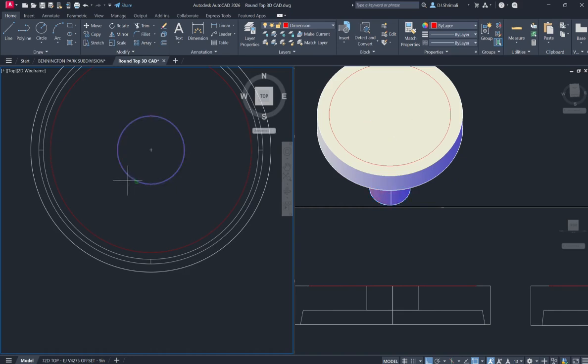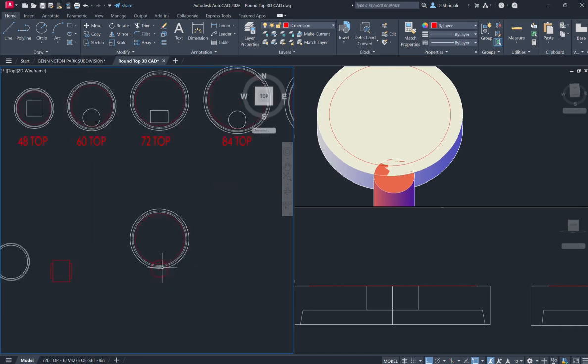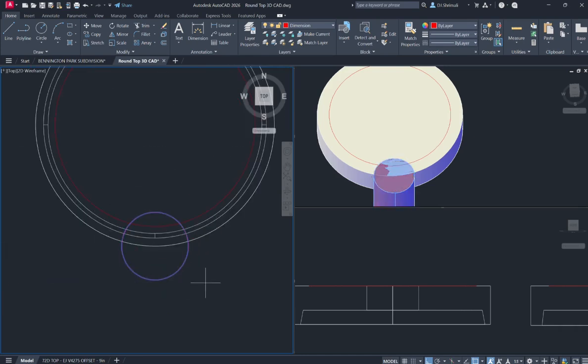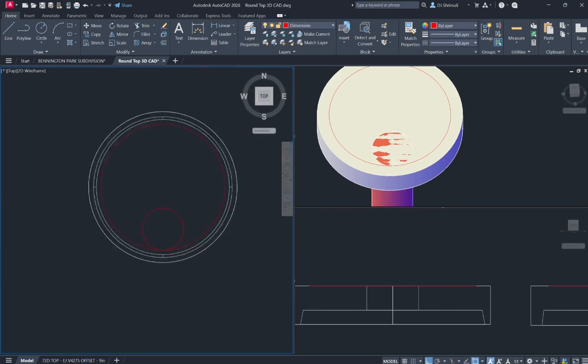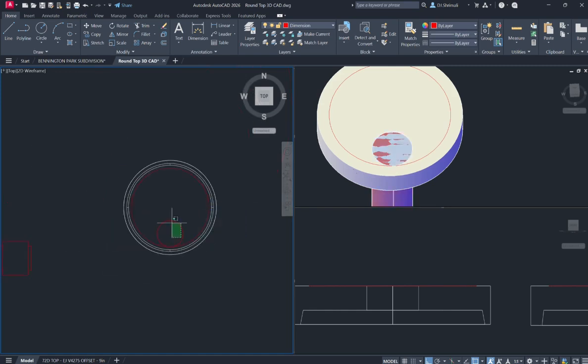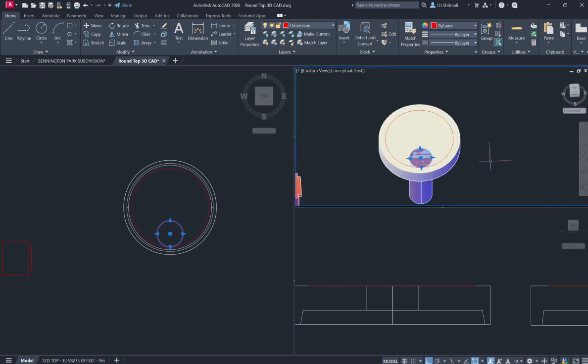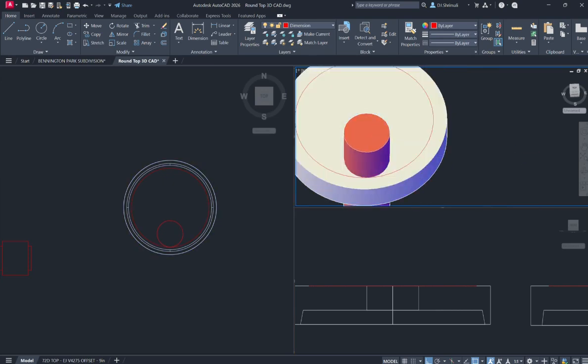Now I'm offsetting it, trying to make it offset first to the edge, and then I'll move the dimension to whatever dimension it is to the edge, and then again to the 7 inches offset, so that it is right at the edge of the wall, so that it aligns to the steps. Right, the steps are going to be at the wall, and if someone is entering the manhole, we need to make the opening align to the step. So here the steps are in the wall, and we are offsetting the cylinder. Okay, and then we'll use the subtract command to subtract the cylinder from the top.